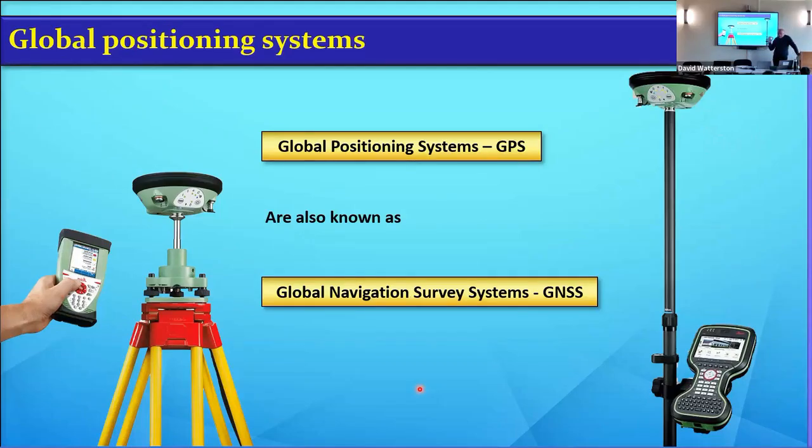So he came to me and says, what am I doing? He says, how can I go over it? I says, well, you should insist, John, when you give out the tenders, you need to say it's fine to use GPS, but you need to confirm that information by conventional means, either by a level or by a theodolite or by something, or go and visit it 2 or 3 times. Because if you visit the same point 2 or 3 times, you can mean out the information. And if it's too far spreading, then you need to think, well, something's going on here and investigate it. But if you just take one shot and accept it and go to the next shot, accepting it, you're leaving yourself open.